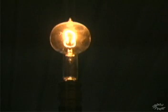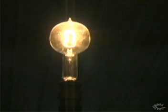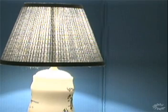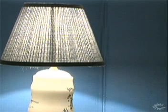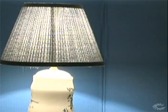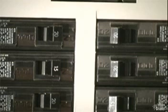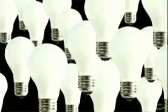This light bulb also has a wire that resists the flow of electrons and turns bright as a result. However, the tungsten wire in the filament of the light doesn't need a lot of current, so its wattage is low. A 60-watt bulb isn't as bright as a 100-watt bulb. Amperage is the measure of current. To calculate amperage, you can divide the wattage of a device by the voltage that it requires. So the amperage for the 100-watt light bulb is less than 1. In a 20-amp circuit, we could have 20 100-watt light bulbs plugged in and on without tripping the circuit breaker.